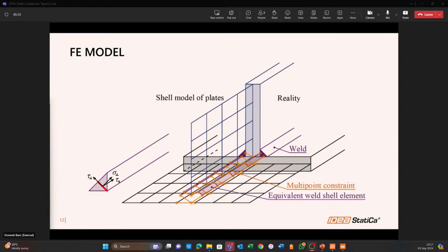This is a visual representation of the weld in the model. A special elastoplastic element is added between the plates. The element respects the weld throat thickness, position, and orientation. The equivalent weld solid is inserted with the corresponding weld dimensions. The nonlinear material is applied, and elastoplastic behavior in the equivalent weld solid is determined.